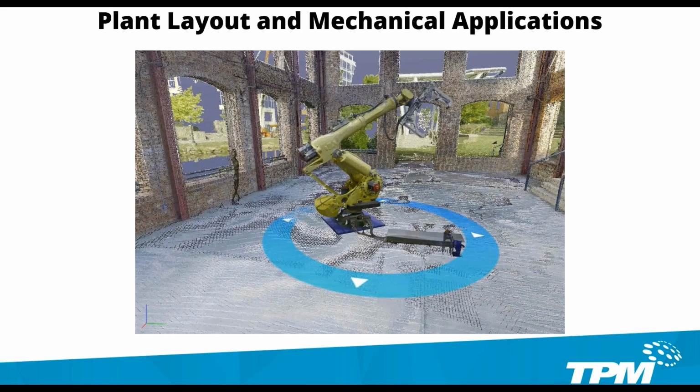Yeah, just from the meshes and point cloud continued uses, especially for layout, that reminded me. I use this in the construction space for ensuring that we had our sleeve locations in the correct spot pre-pour.